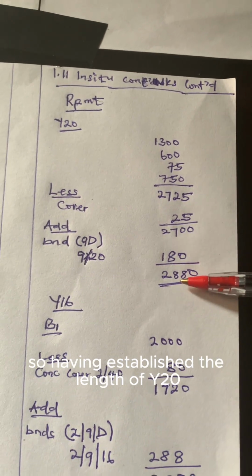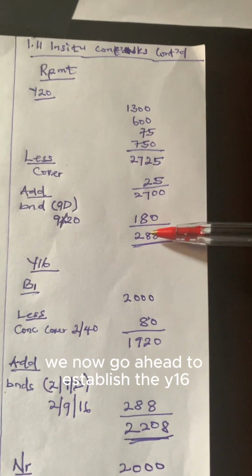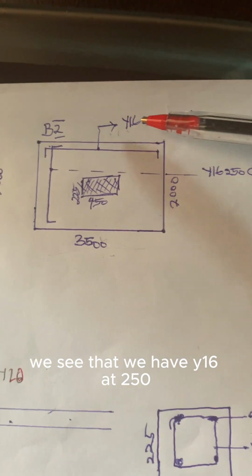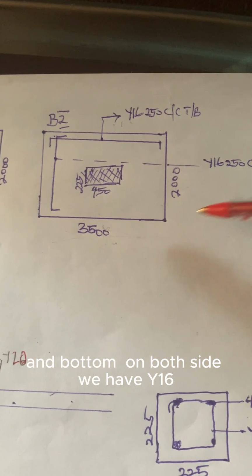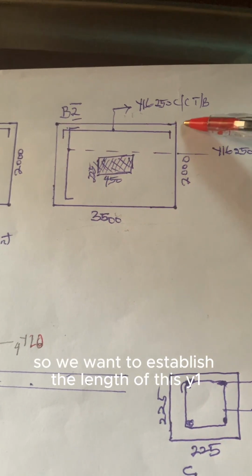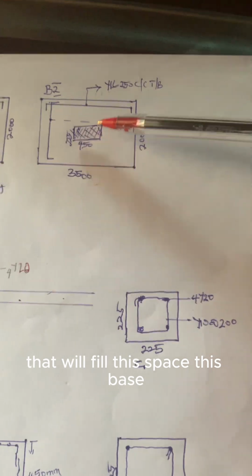So having established the length of Y20, which is in the column, we now go ahead to establish the Y16, which is in the base. If you look at the base, we see that we have Y16 at 250 center to center spacing, both up and bottom. On both sides, we have Y16. So we want to establish the length of this Y16, and then we multiply by the number of Y16 that will fill this space, this base.